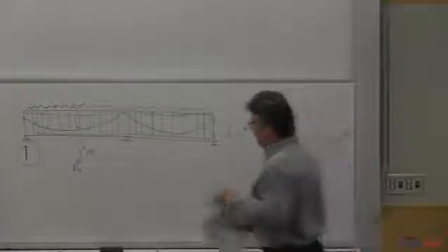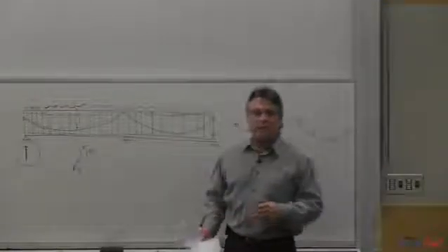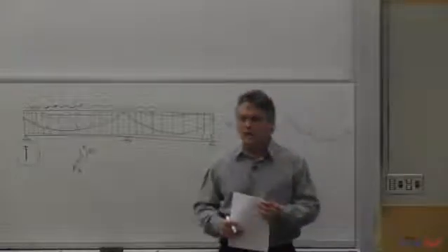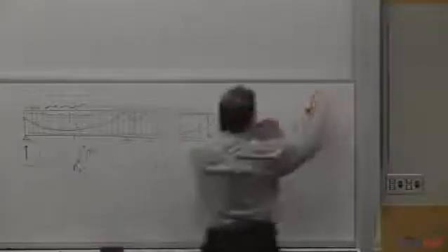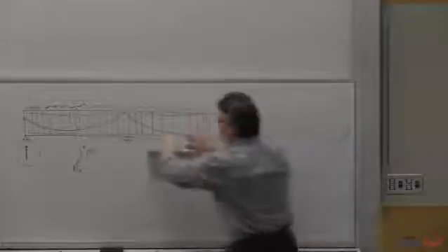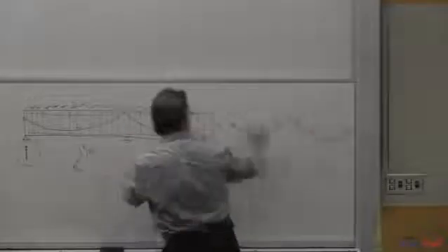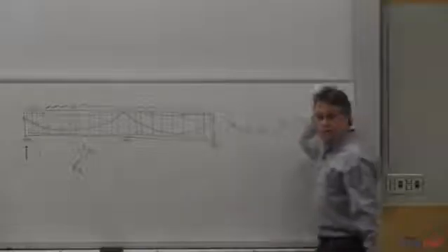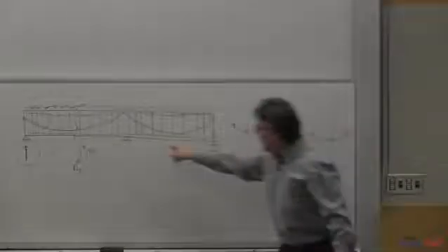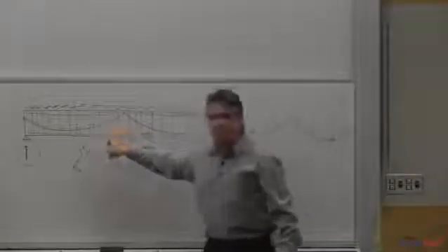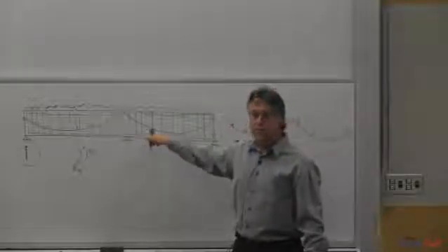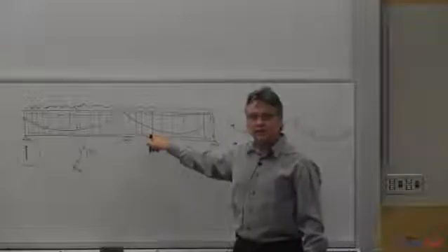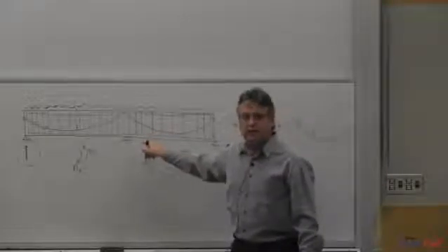And then we looked at the other way of doing it, the way that T.Y. Lin came up with. He said you can separate what the tendons are doing to the concrete and what the concrete is doing to the tendons. If you separate these out and you take this part of the load and you toss it off to the side, and you leave yourself with a fictitious loading condition that doesn't really exist, but it's extremely valuable for calculating stresses, you can calculate stresses.